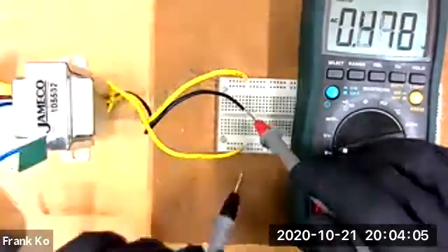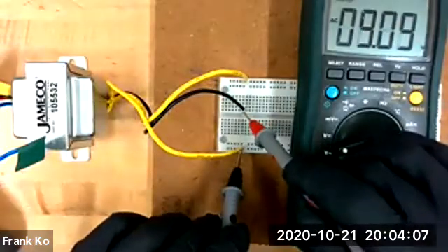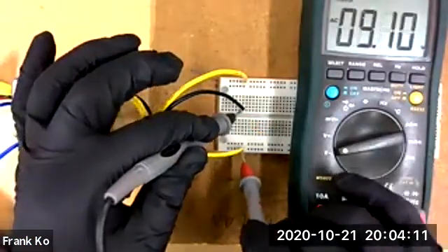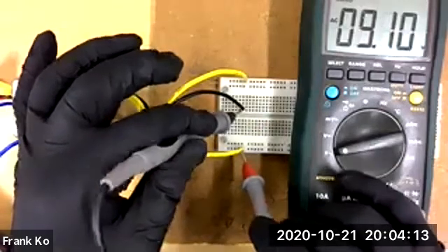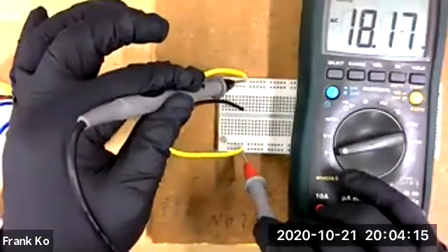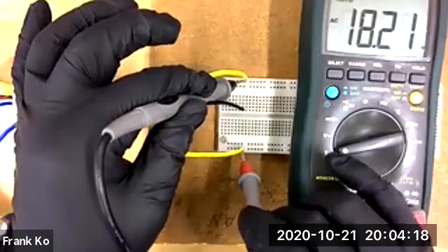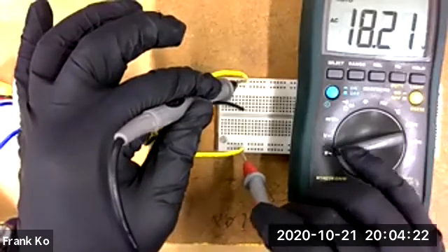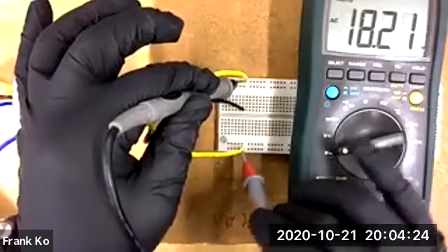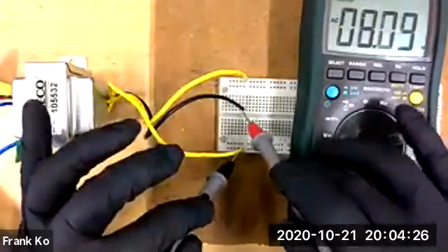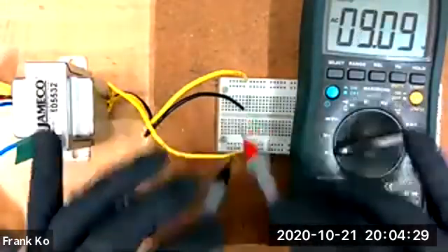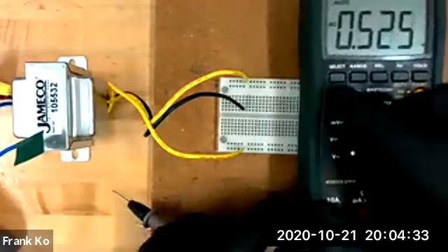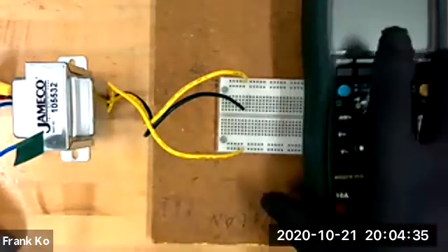So, and does it make any difference where you put the red probe? If you flip it around, do you see a negative voltage in any of all of this? No, not at all, because this is AC. AC voltage is not going to demonstrate a polarity on your multimeter. Everybody all right with that? Yay. All right, so now you have proven that you have successfully wired your transformer,